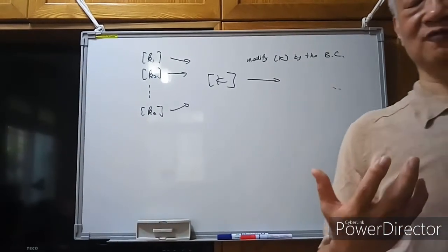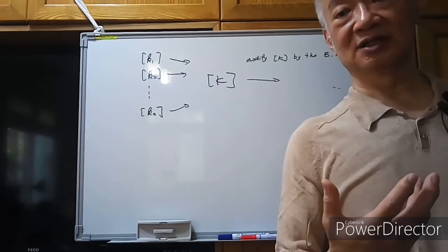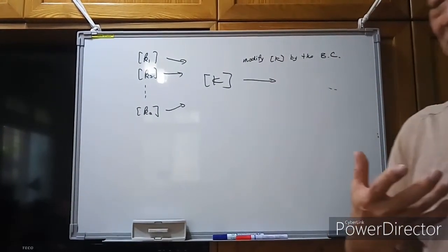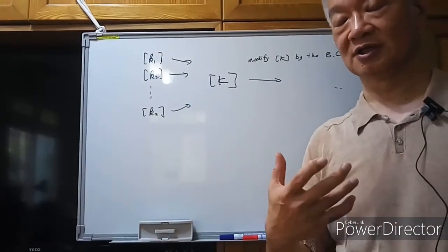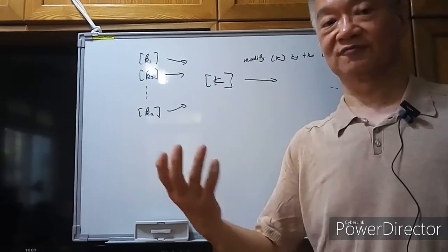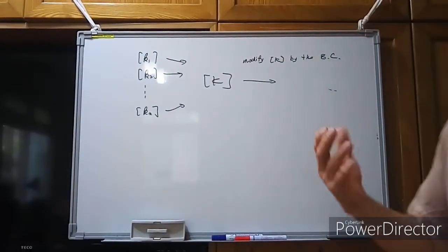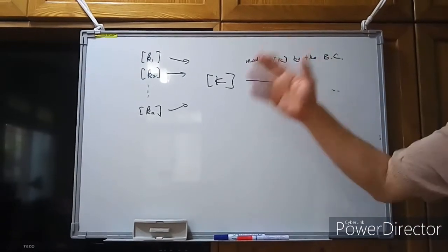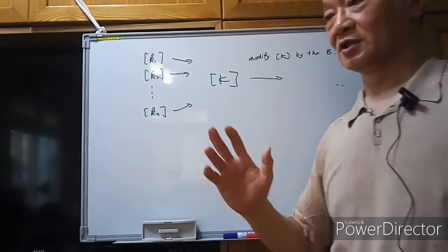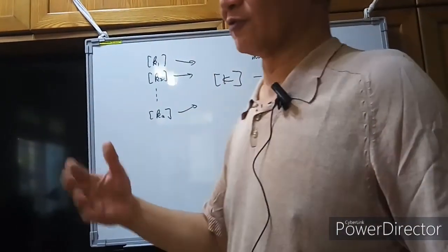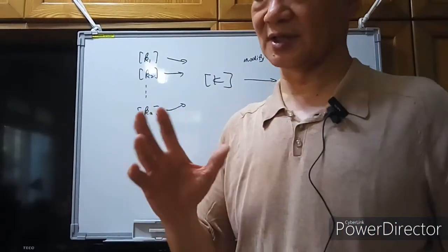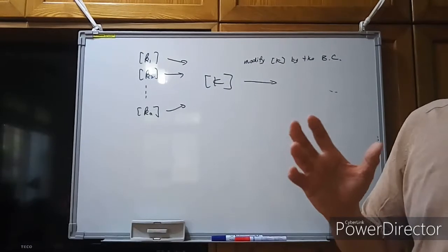You cannot solve the problems for unstable structures. For unstable structures, even when the applied loadings are equal to zeros, you can still see the rigid body motions. So it is not possible to solve for a structure without any support. So you can say for all practical problems, we must have some types of boundary conditions.